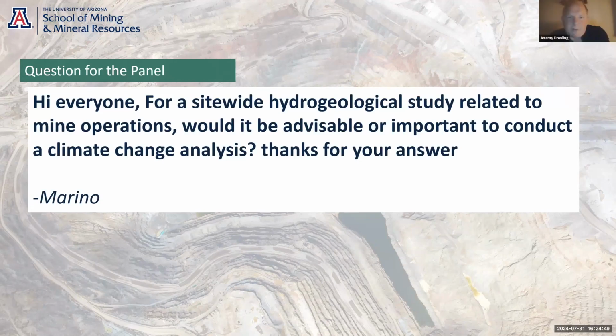I think in some regions it's more of a surface water flow question that is becoming quite important. So in the Southwest USA, for example, there's a lot more high intensity cloudburst type events. 1 in 100 year, 24-hour storms occur quite frequently, not once every 100 years, but almost every year.